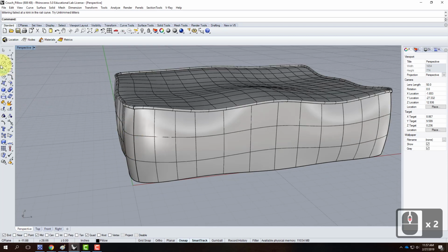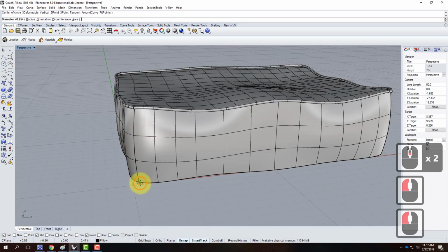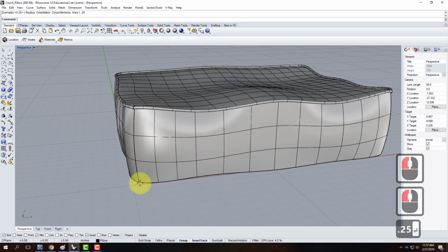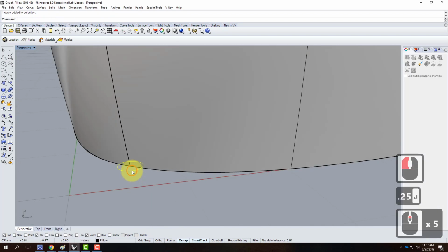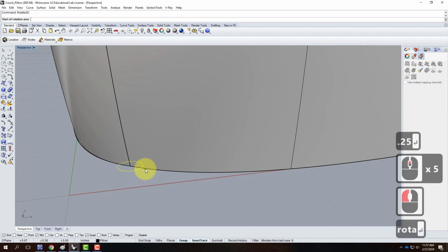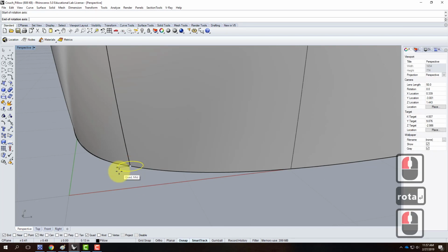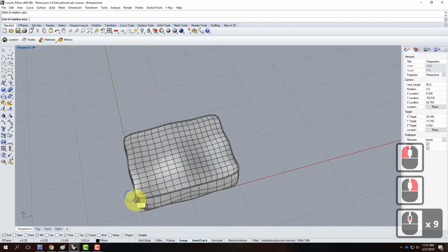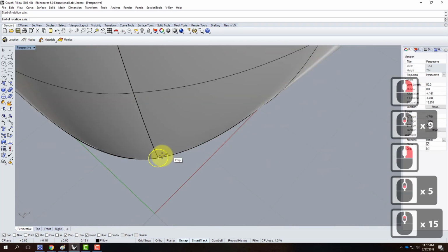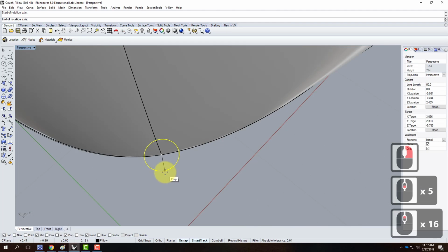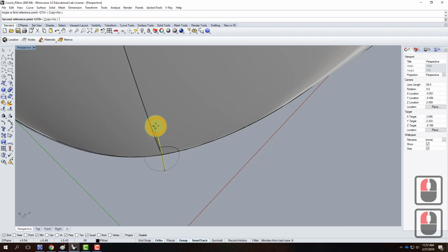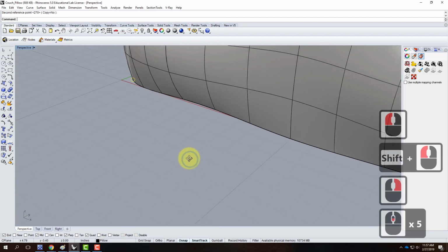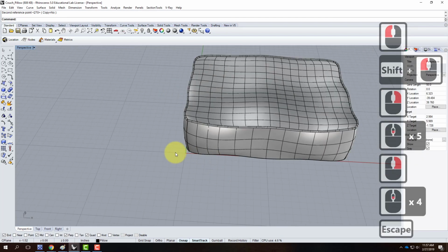So same thing. I'll go back to my circle. It would be 0.25. Again, I need to rotate it. So I'll rotate 3D. And I'm going to do this all in one. So I'll snap to perpendicular, and I'll come out. Maybe it'll help if I'm looking down on it here. I'll come out roughly at about 45 degrees. We'll snap again to here. I'm holding down Shift so that it rotates up. There it is. I need to sweep one.